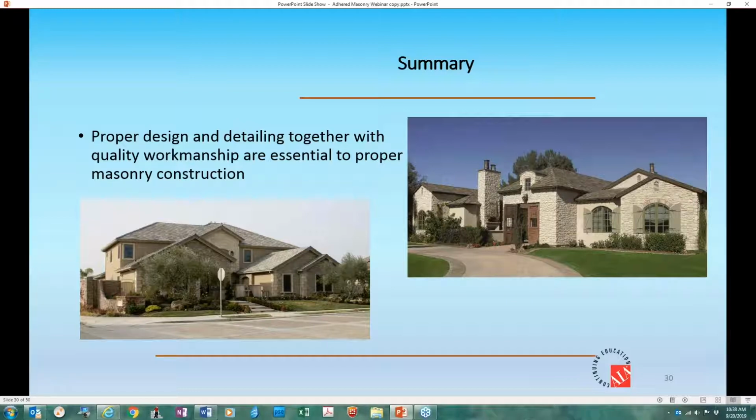Okay, Stephen, first question. Where do you place the drainage mat in a thin adhered veneer system? Between the outer layer of weather-resistant barrier and the extruded metal lath.